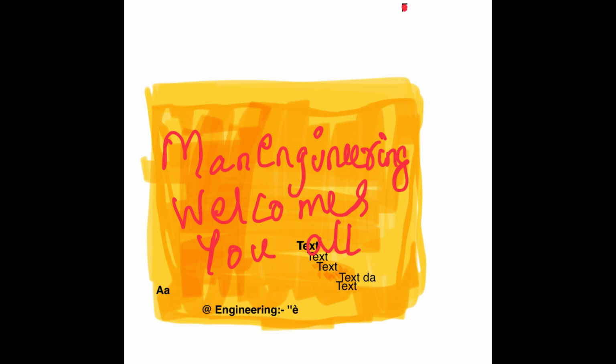In this circuit we use Kirchhoff's voltage law: the algebraic sum of the voltages around a closed loop is 0. In this way we form the mesh equations and from them the matrix. We already saw in the previous class how to form the voltage matrix and current matrix, and we use Ohm's law to determine the branch current and element current.